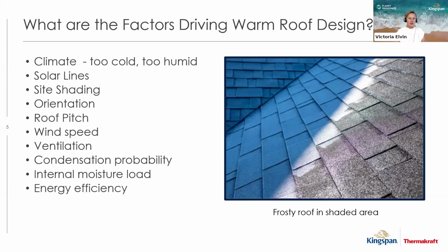If the roof pitch is very low, again improving our height boundaries on a very compact site, then we might not see the ventilation that we need within that roof. And the wind speed can be impacted because we have a lot of houses built together. The wind speed will affect the ability of a roof to ventilate. So lower wind speed, less ventilation driving that roof, and then the condensation probability starts to rise.